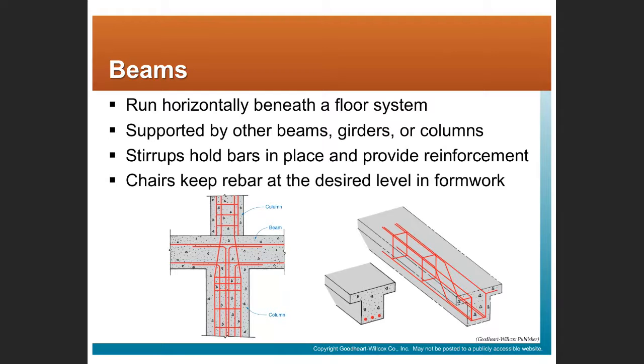You see in this picture here, we have more rebar at the bottom, right? The bottom of the member is where there'll be more tensile forces, right? Because we're pushing down on that member, so it'll be in compression on the top and tension on the bottom. And this is a section kind of showing how a beam and a column would get tied together. Again, the reinforcing is there to help transfer the load in the beam to the column.